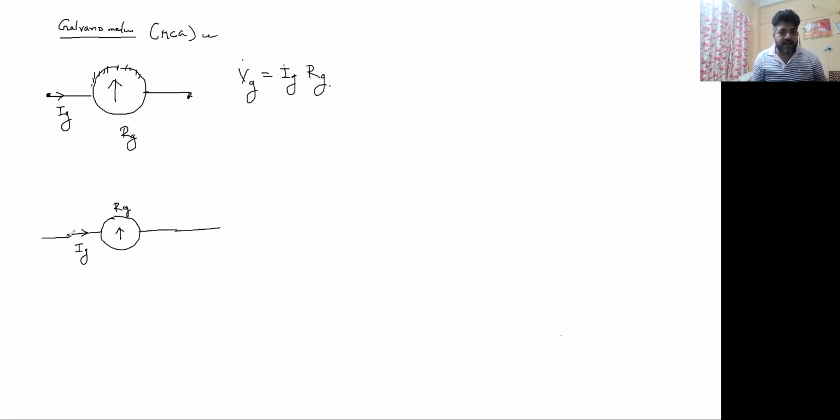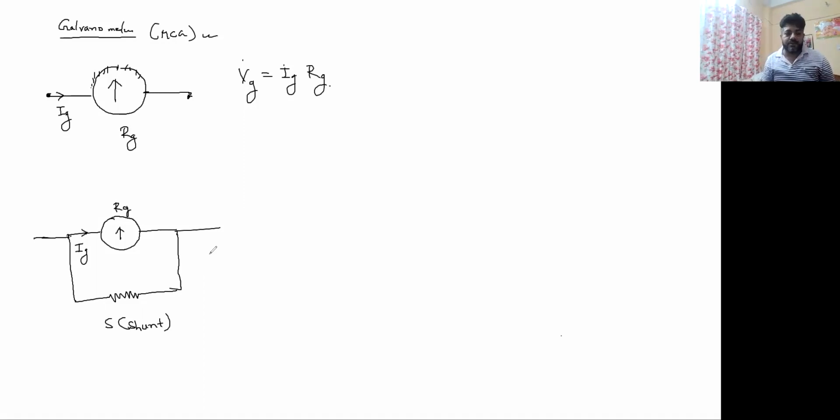So for that, you connect a very low resistance called shunt in parallel with the galvanometer. So then what happened? Your net current is increased. So that means now the ammeter: if this is my I, from here you have IG. So the rest of the current flows through the shunt, less resistance, maximum current, I minus IG. Clear everyone?